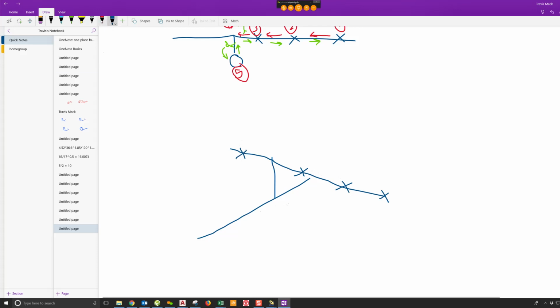We're going to figure out what is the flow and pressure needed at this point right here. This is our target point. Okay? We'll go 1 inch, 1 inch, 1 1/4. Let's say that this is like a center fed system, so it'll all be the same thing. So this is 1 1/4, 1 inch, 1 inch. Let's make this 1.5 inches. These will be a typical 12 foot. This will be a typical 6 foot. And we'll do a 2 foot riser nipple. Okay? Does that make sense?